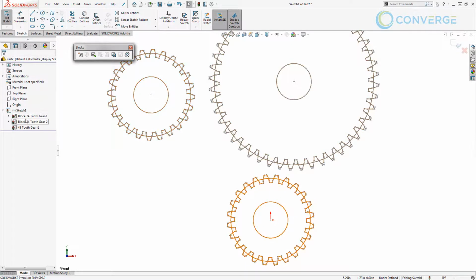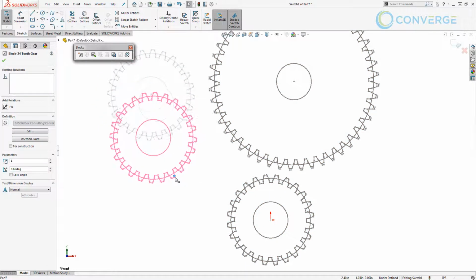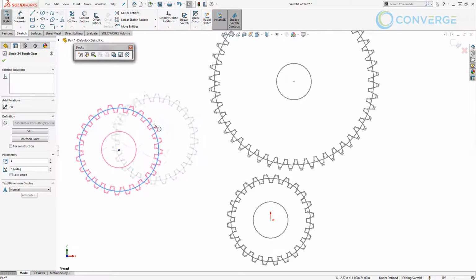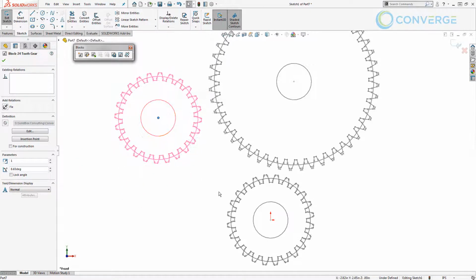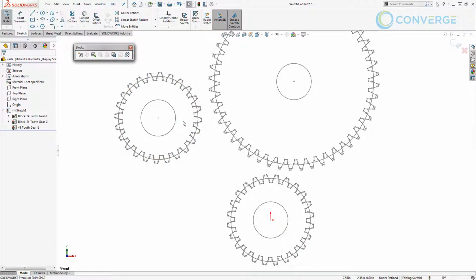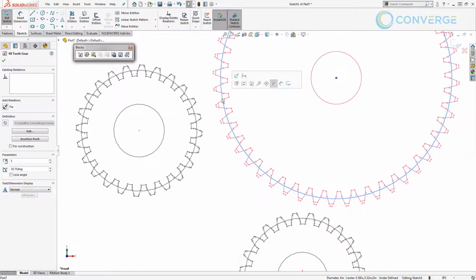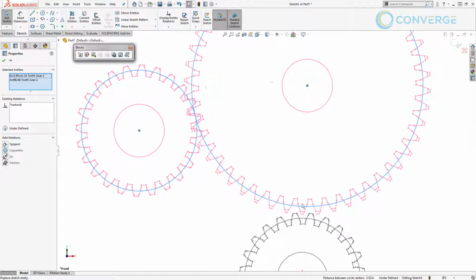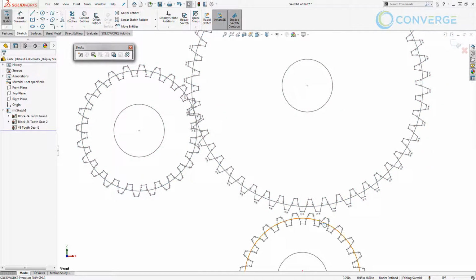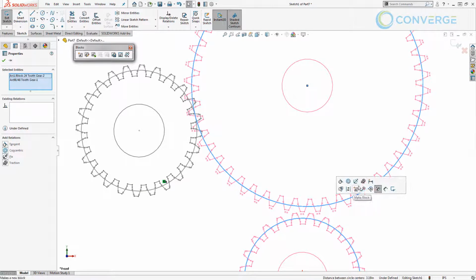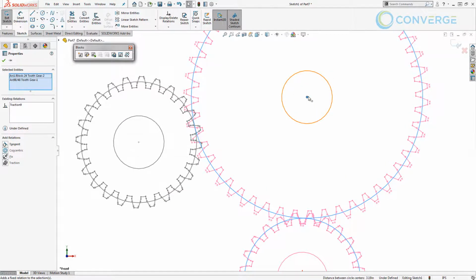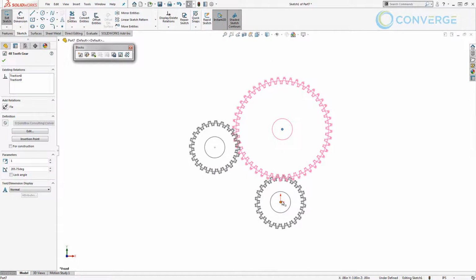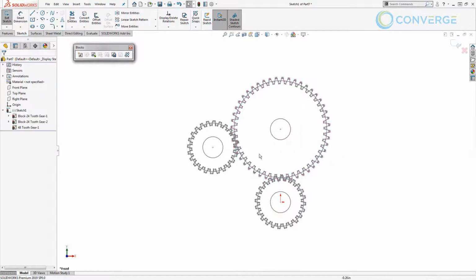You can see it's included in that block. And then this one over here, it's free to move about. You can see there's a circle there, and everything's good because these are the same blocks. So once I add it to one, it'll add it to the other. Now what I want to do is engage those blocks. And again, the selection is important. We're going to make sure that we select the 2 and the 4-inch diameter circles, and we engage those 2. Then we follow that same process over here. We'll grab the 2-inch and the 4-inch. We'll use that engage blocks. Then we can go back and add the constraints and relationships that we had before by making vertical and horizontal.